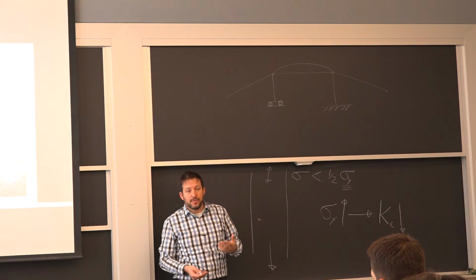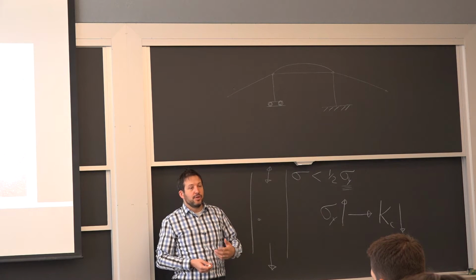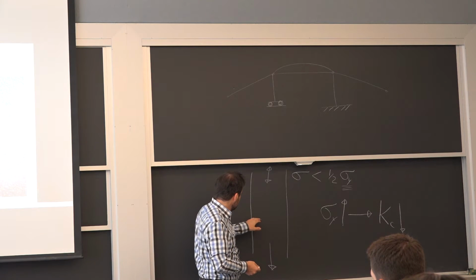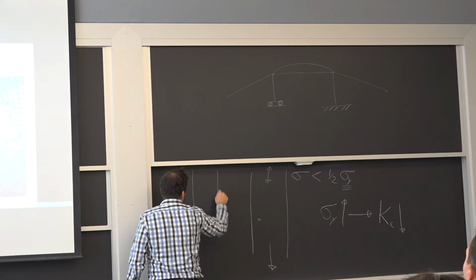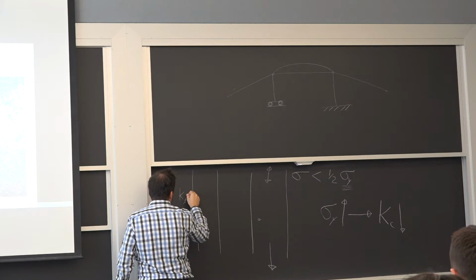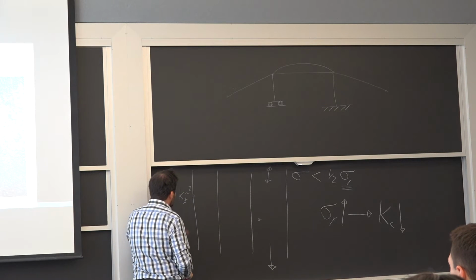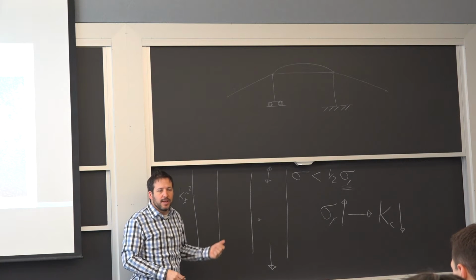So what happens? 1/4 is because we had a notch on the surface. So in addition to having some local, our situation with this shaft is, it was like this. You had a little notch. So you get your KT here. Maybe it's 2, and then you get an extra stress concentration at the little particle in that notch,